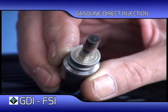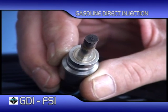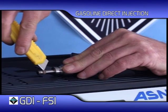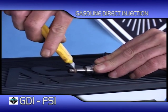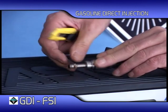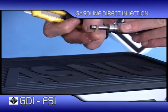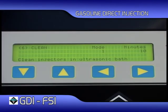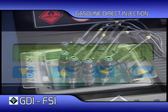If you find that the end of the injector has carbon buildup, we recommend the ends of the injectors are cleaned in the ASNU ultrasonic cleaning bath. Before cleaning, remove the Teflon head seal from the recess on the pintle shaft of the injector. To prevent air leaks, this Teflon seal must be replaced every time the injector is removed from the engine.